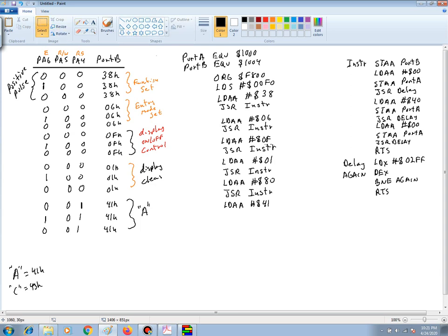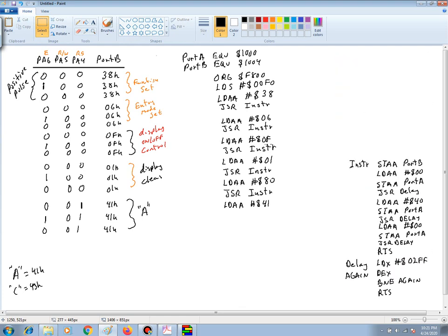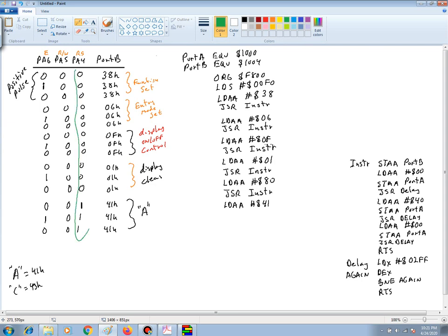So let me move all of this a bit further down, because I'm going to put the data subroutine on top of this. The interesting thing is that everything else pretty much stays as is except the actual value that we're sending, because the only change here was in this area: your RS line changed from a 0 to a 1. That's the only thing that changed. So I'm going to copy all of the instruction subroutine and just make those changes. And I actually meant to copy it.